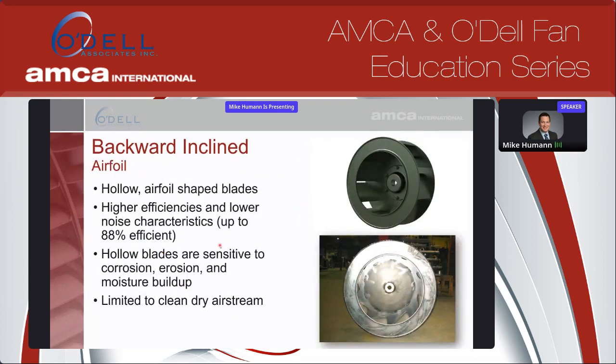So now we go even to a different backward incline design, and that's the airfoil. The airfoil is shaped much like an airplane wing. You can kind of see here is a good example. You can see the top skin and the bottom skin, using the weld stains there. So this is a very efficient build, but it's also very sensitive to any corrosion, moisture buildup, or erosion. You really want to have this in a clean, dry airstream. These are some of the most efficient fans you will find. And with that efficiency also comes some better noise characteristics versus a radial or even the single thickness blade.